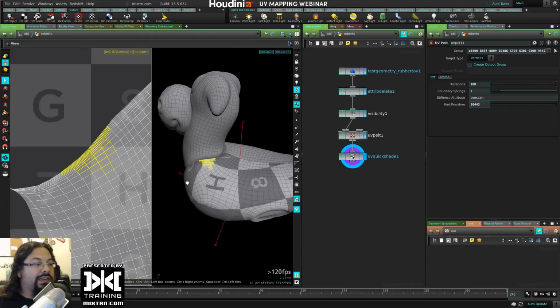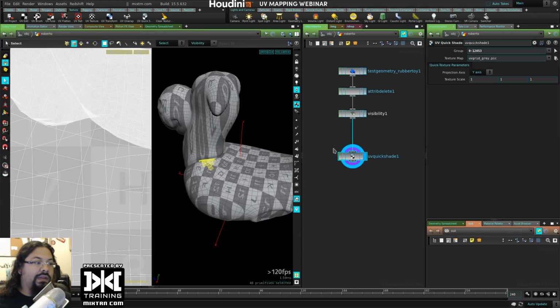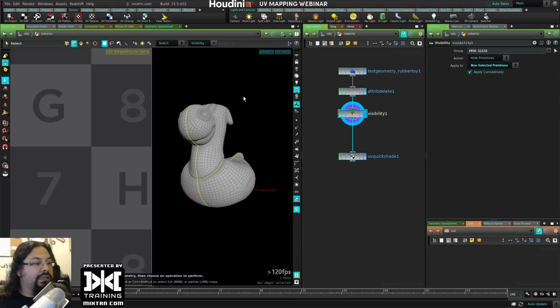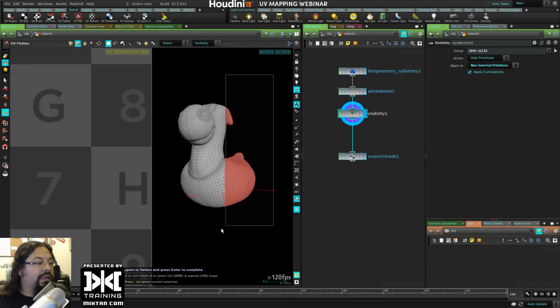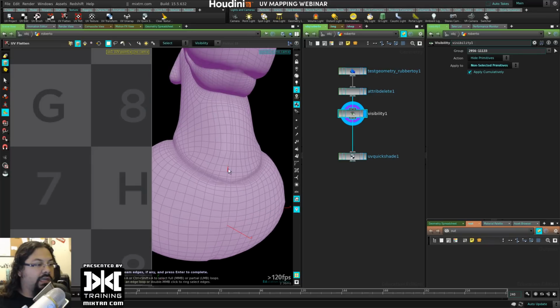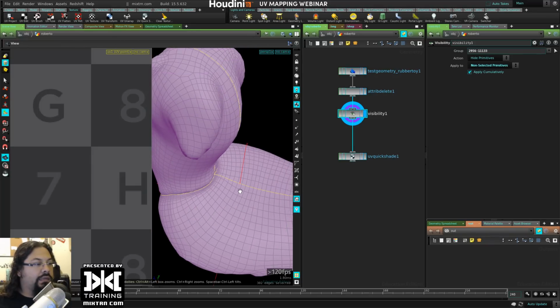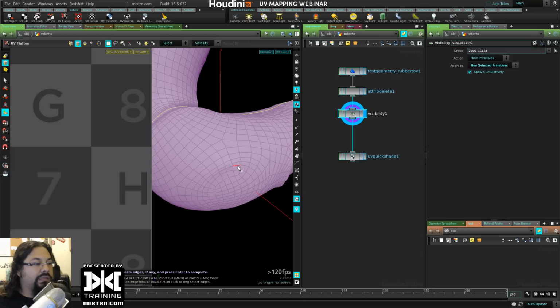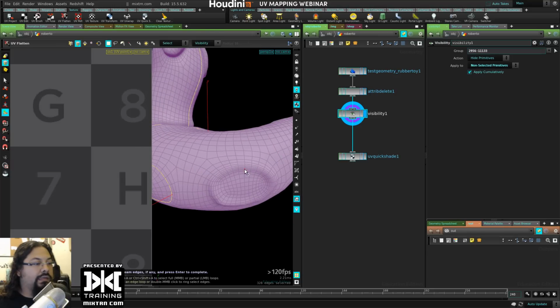But what I like to use now is the UV layout. The UV flatten. And it's actually, yeah, it is here. So let's go and deselect everything. Just use the UV flatten from here. Select the polygons. Enter. Now you select the seam edges. The same. Select here. Neck. Now I'm gonna select legs again.